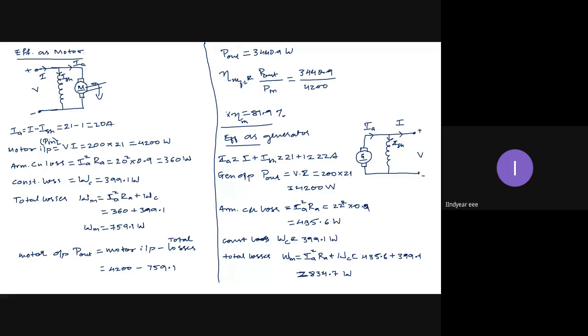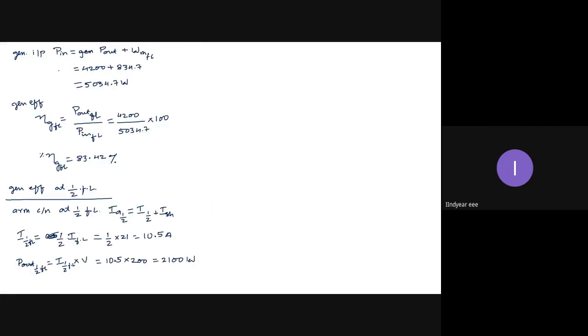This concept I cannot apply to motors, because a motor even at no load condition draws some current. Whereas for a generator, the line current at no load is 0. Okay, so we should keep that in mind. Therefore, the power drawn by the load is also half, so power generated by the generator is also half. So I have to deduct power also.